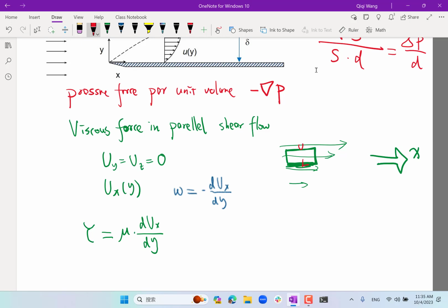Yeah, upstream, right? The flow outside is moving slower, so the slower fluid is going to decelerate it. It's going to drag it back, right? So that tau is going to be dux/dy acting in this direction. And contrary to that, at the same time, the flow in the control volume is going to drag the flow underneath it with the same viscous force in the downstream direction.